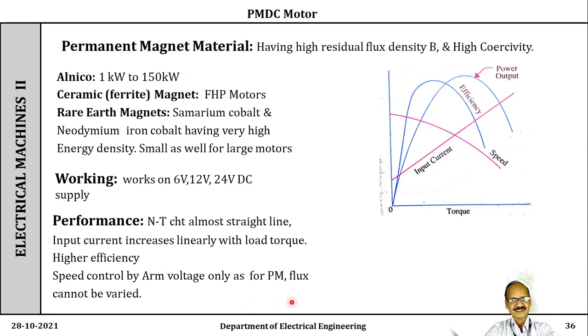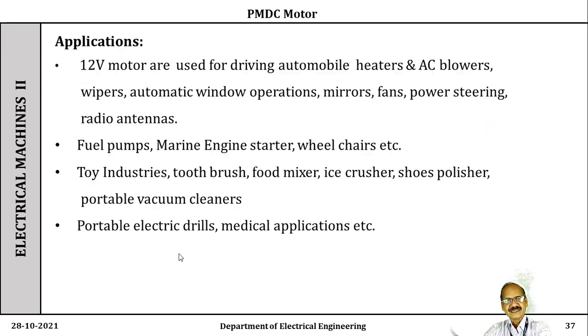We cannot obtain flux control here. Therefore, the armature voltage control method is generally used, meaning by reducing the armature voltage, and this can be obtained by using chopper circuits. Generally the speed requirement is less than the rated speed, and that's why this is preferred, and there is no alternative also. Then the next point is, what are the disadvantages of this?